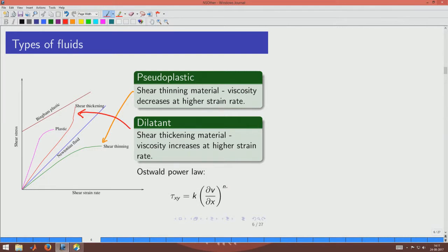You could see that you can no longer use the linear law and you need to use a power law, and here is a term that makes this type of fluid different from the Newtonian fluid. These fluids at low strain rate could perhaps be modeled as Newtonian fluids, but at high strain rates you need to modify, and the power law will come in.